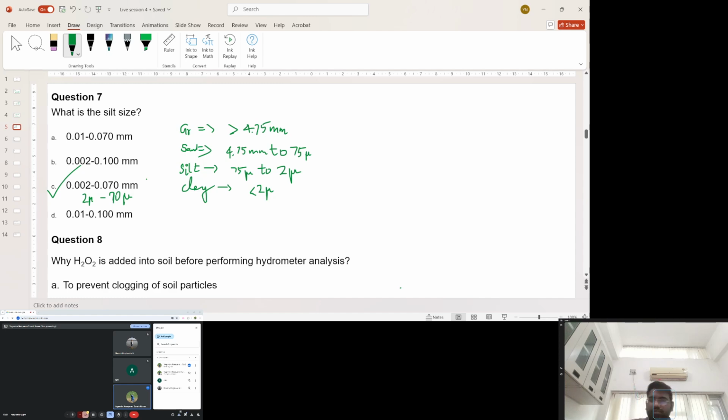Further classification of whether it is a clay soil or silty soil is done by further index testing, which we'll be studying next week, which is Atterberg limits, that is plasticity limits, consistency limits. The type of clay can be determined by using several techniques to determine the mineralogy as well as the chemical composition by using XRD, etc.